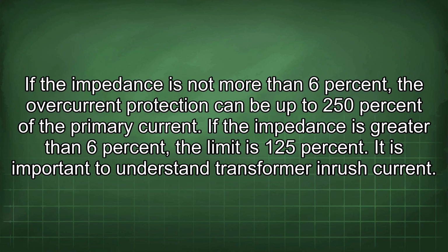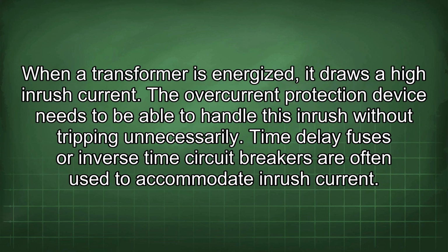It is important to understand transformer inrush current. When a transformer is energized, it draws a high inrush current. The overcurrent protection device needs to be able to handle this inrush without tripping unnecessarily. Time delay fuses or inverse time circuit breakers are often used to accommodate inrush current.